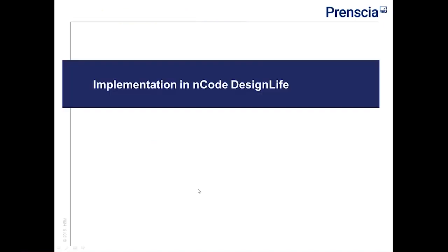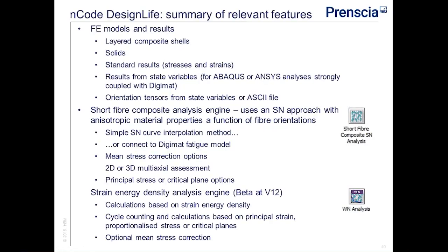Okay, so this is where we actually get around to describing the implementation of the methods in nCode DesignLife. So a bit of a boring slide here. First of all, in terms of reading finite element models and results, the relevant features here are that we can now deal with models which are either layered composite shells or solids with a layer representing each layer. We can read standard FE results, so stresses and strains from the models.